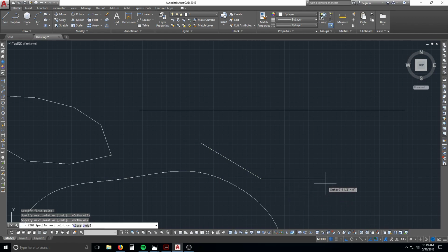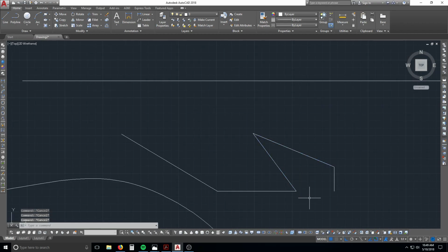So there, and then for my next one, I want to turn my ortho back off. Again, I want to come over this way and do another custom angle, but now I want my ortho back on. And then you can click there and choose the intersecting point, so now it's exact. So, you know, a million and one different ways of making your lines. So there you go. And again, these are just single lines, and if you wanted to join them, J, enter, now it's all one line. That would have worked with your polyline as well. So that was line.